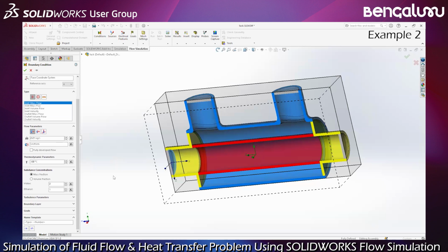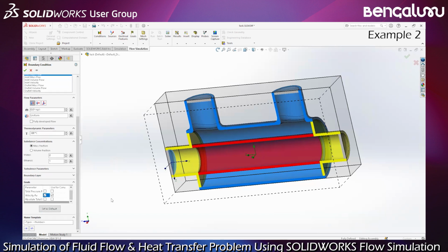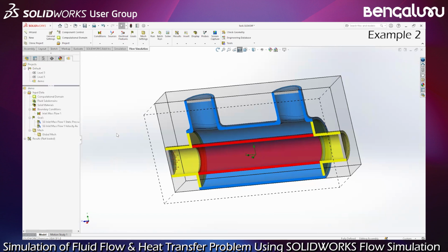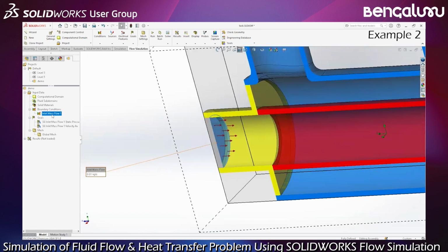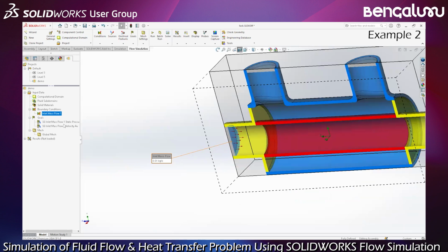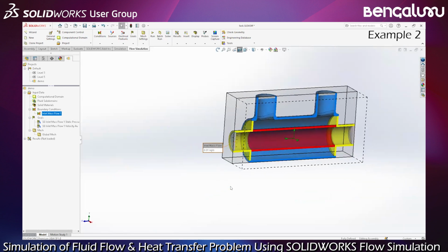I told you last week as well that I can directly create goals on this inlet, and you have the appropriate one. For example, I can say I would like to get the pressure, I would like to get velocity, and so on. Validate. You can see the symbols there. You can see the creation of this condition, and as well creation of two goals, so that I can follow the value of what I have defined here, pressure and velocity.